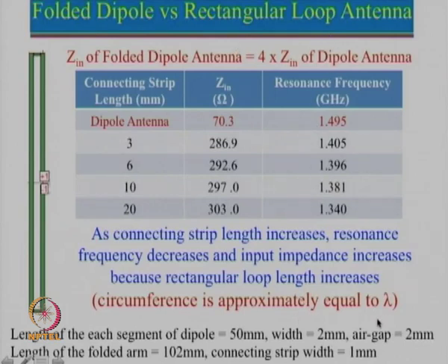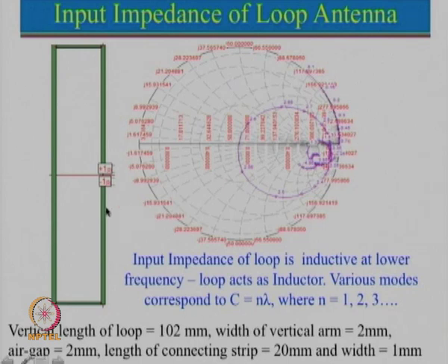Also please recall, I did mention that when the circumference is equal to lambda, the limit can be between 20 pi square, which is 200, and a maximum of 60 pi square, which is 600. So between 200 and 600 ohm is what we are getting for circumference equal to lambda. Here are some of the plots.